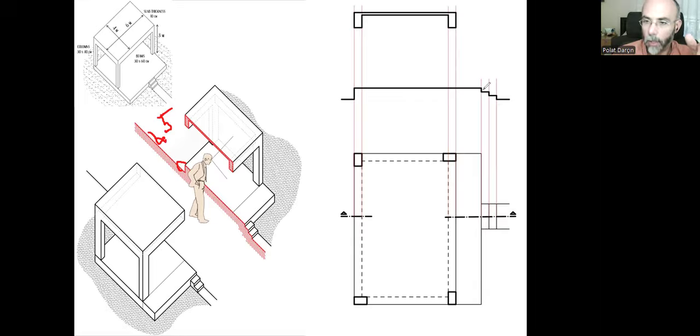Right at that point, I need to go downwards 15 centimeters because that's the height of each riser of the steps. I go 15 centimeters downwards, of course, in the scaled version. And then, using that guideline, I draw a straight line to indicate the cut surface of the step, the tread, the upper part, and then go one more 15 centimeters downwards and do the last step and the road. And that's again with open ends, meaning this line continues in this direction. It's a continuous line. It indicates the upper surface of the road and the earth.